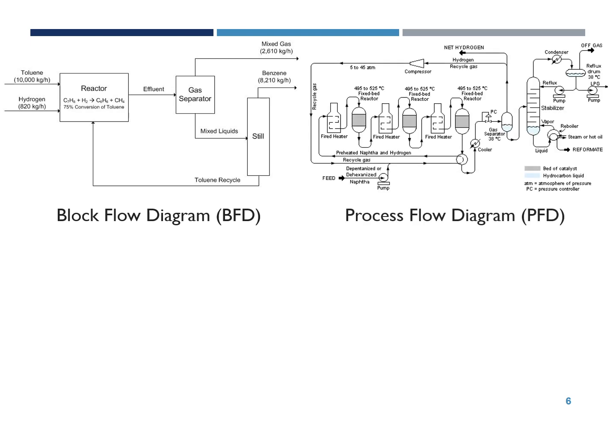Second, a process flow diagram or PFD. This diagram indicates the general flow of plant processes and equipment. The PFD displays the relationship between major equipment of the plant's facility and does not show minor details such as piping details and designations. Another commonly used term for a PFD is a flowsheet.